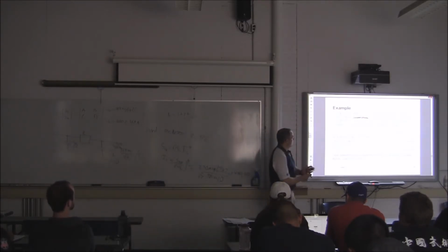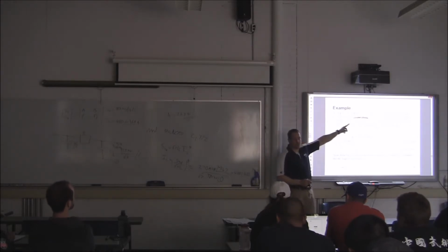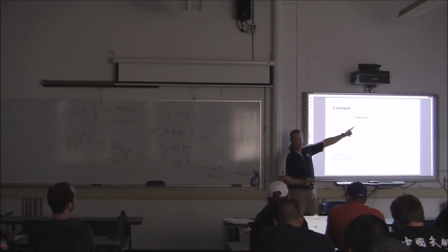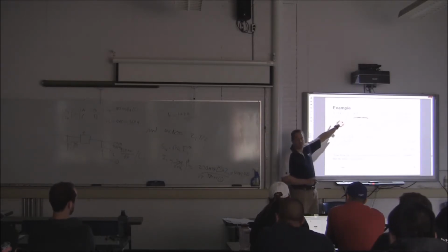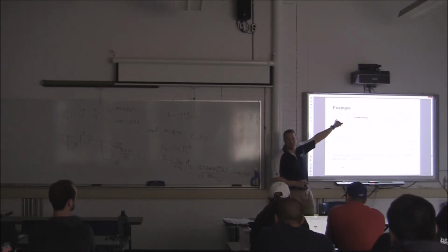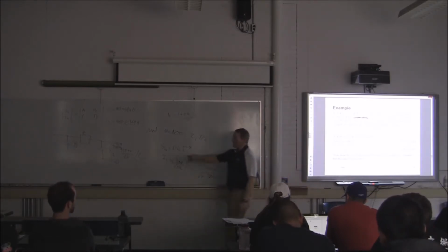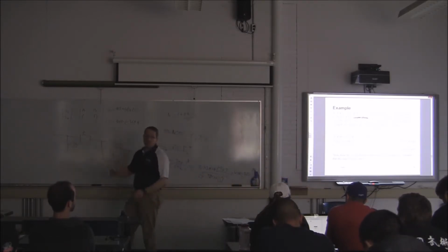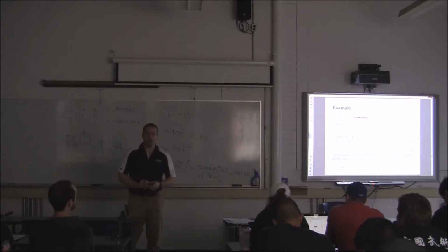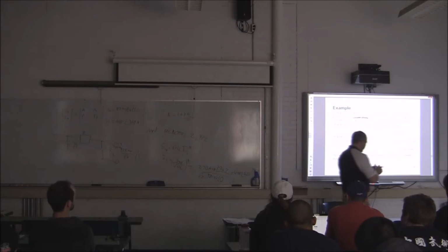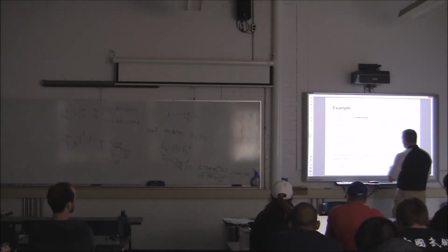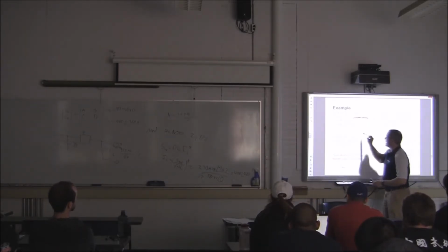So I've got r, which is going to be a part of my z. I've got L, which is a part of my Z, but I've got to put it in terms of a complex reactance. I know what C is, but again, I need to make that a complex admittance, which means it has a J term and has the unit of mhos. So I can't put capacitance in there. I need to solve for its reactance.